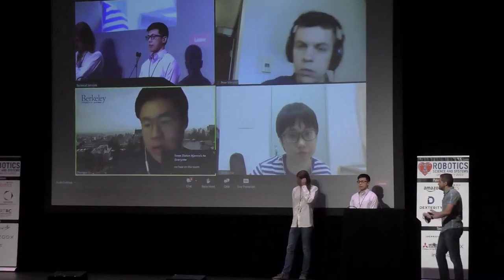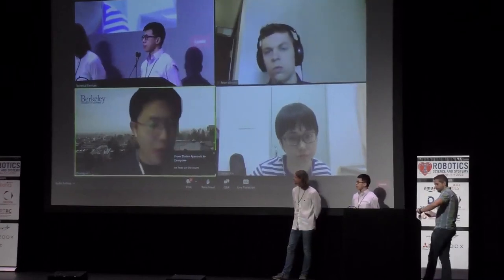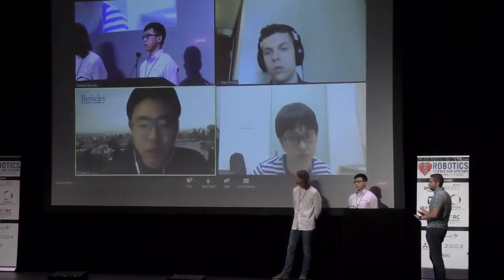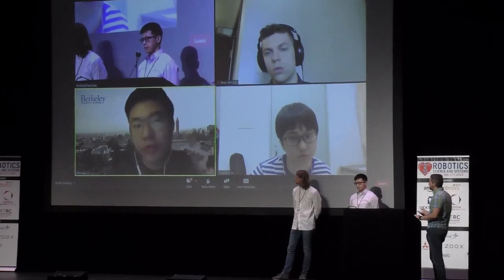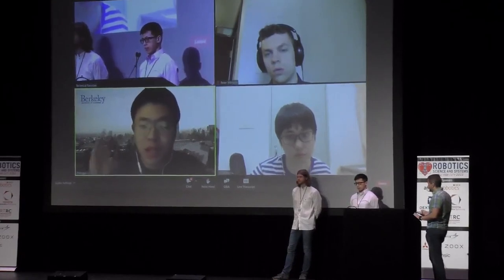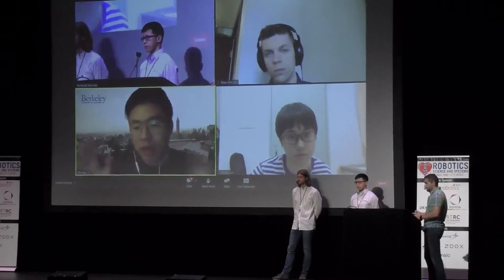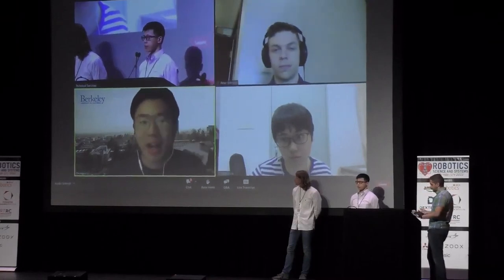Thanks for the question, very good question. So we actually have details in the paper, but to be short, we first assume a high dimensional system, like 10th order. Then we do linear fitting, find the system, and then we do model reduction by looking at Hankel singular values.